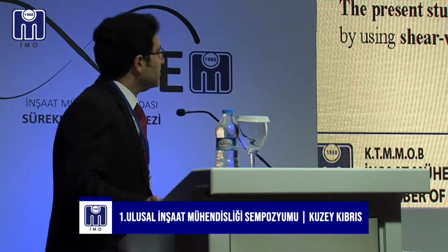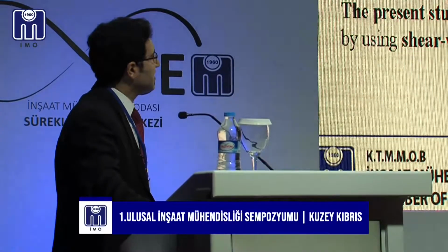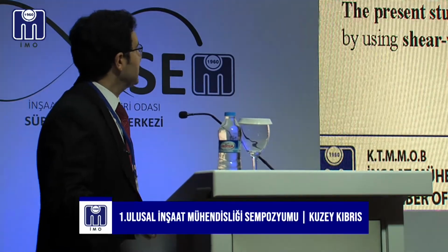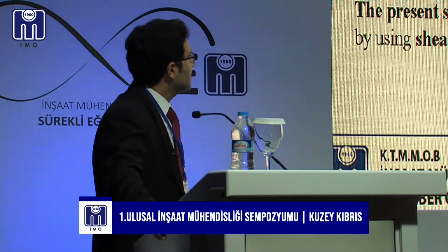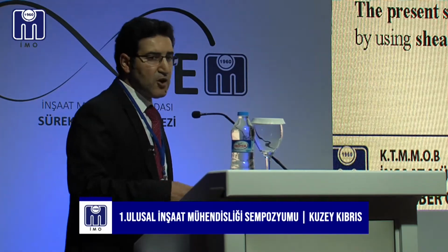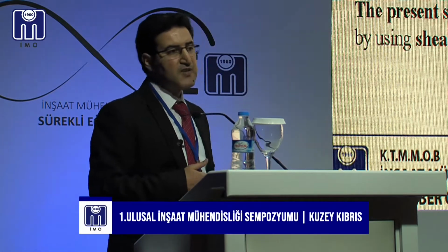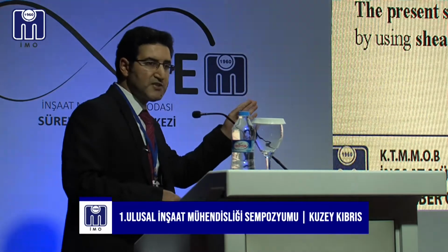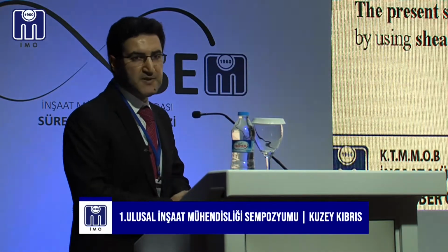Much research has been done on post-liquefaction volumetric strain in laboratory tests in terms of relative density and maximum shear strain, such as Lee and Albaiza, Tatsuoka, Nagase and Ishihara, and others. All of them produced a methodology for estimating liquefaction-induced settlement based on important parameters from penetration tests, such as SPT value and CPT value.